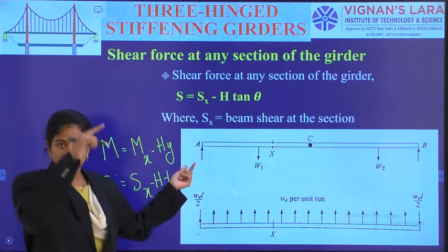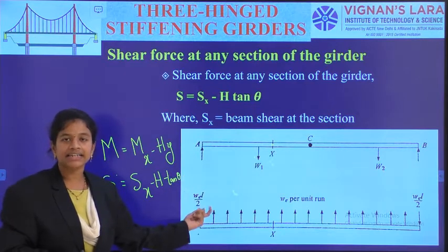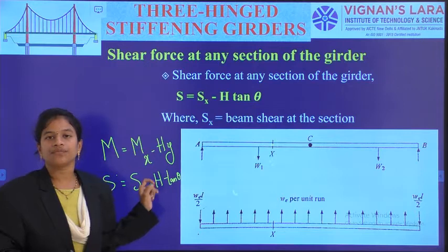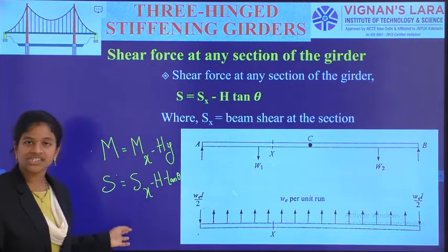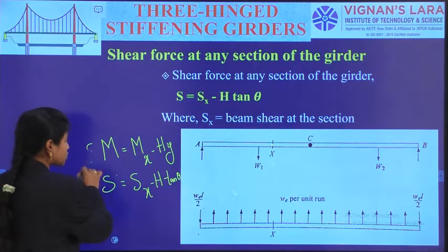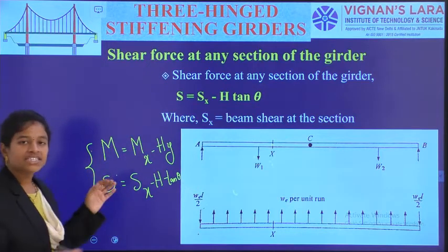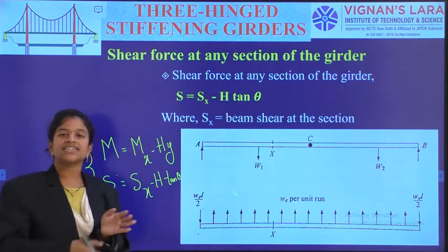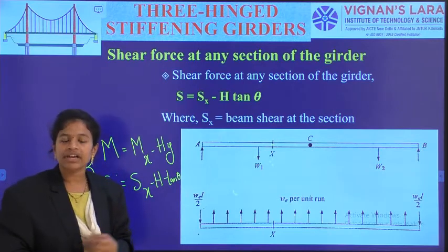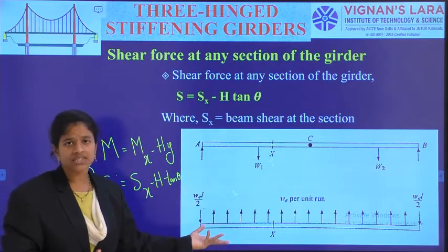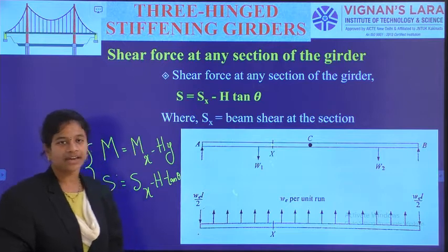We already know the corresponding dip of the position, and tan theta is the slope at the particular point where we are calculating these moments or shears. So, these two are the main outputs for calculating moments and shears. As we know the individual moment answers and individual shear answers, can we develop the bending moment diagram and shear force diagram? Yes, we can develop the bending moment diagram and shear force diagram.